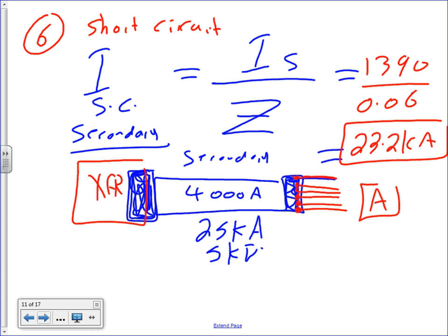From this side, this is the 400 amp fuse. I'm showing you a fuse, guys. Here, a 400 amp fuse. One side is tied to the transformer. The other side is tied to all these 6 sets of 500 kcmil, with special lugs. Does that make sense?